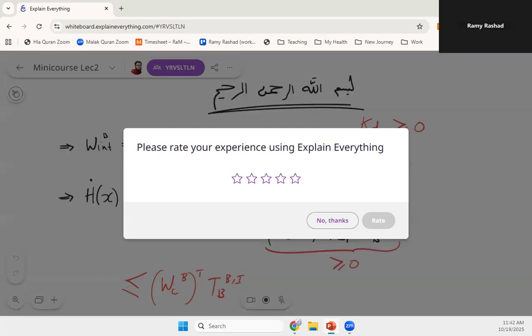Then it can be non-passive and cannot guarantee contact stability. I think yes. Impedance means inertia, stiffness, and damping. The only thing that you can make time varying without changing the passivity is the damping. You can make the damping time varying. If you remember, we had this nonlinear damping part. I could have removed this nonlinear damping by adding negative nonlinear damping in the controller, and it would still be passive, so it will not change anything.